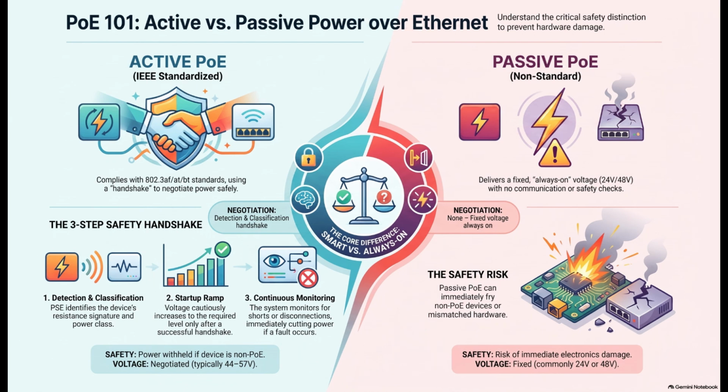If a technician accidentally plugs that active cable into the standard data transformers inside a non-PoE laptop's network card, the voltage has nowhere to go but into the motherboard, physically destroying the component. Yes. By explaining the mechanism of destruction, you ensure the reader respects the warning. That is exactly the kind of why and how the reader needs. A warning label is easily ignored, but an explanation of the underlying failure mechanism creates a lasting memory.